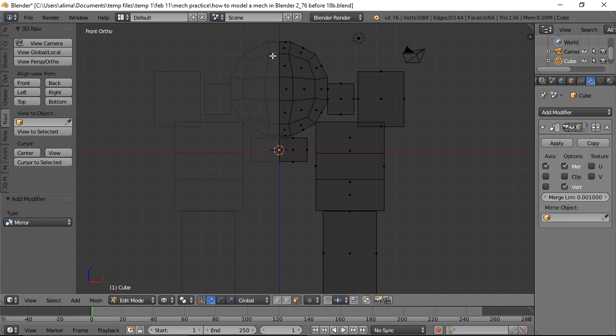That's why this is pretty much perfectly matched up to right here. When I first started using Blender, I didn't understand about this origin point, and I would do things to move the origin point, and that would cause issues. But to have the mirror modifier work correctly, you need to have it right in the center. So here's our virtual geometry from our mirror modifier.